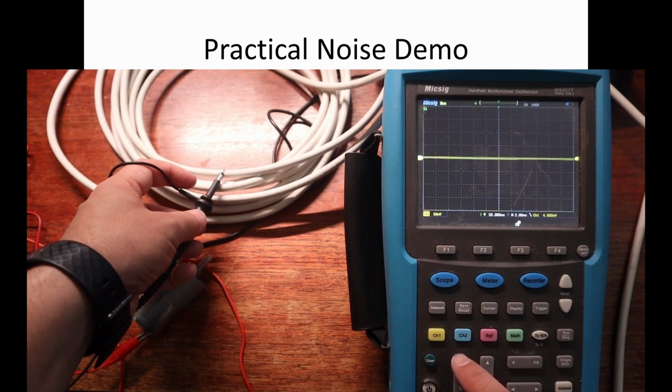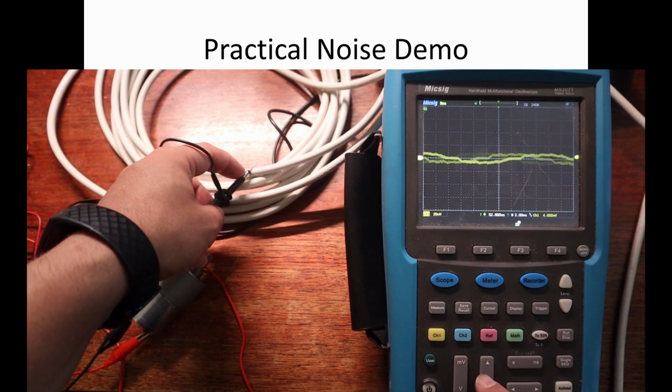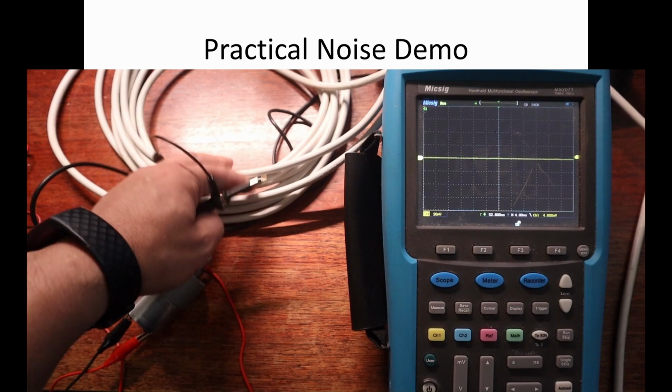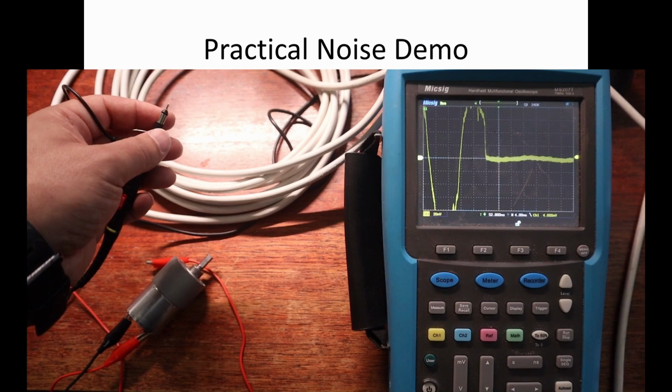We'll have to adjust our scale, and we should see we're getting a little bit of noise from being coupled in. And if I change our frequency a bit, we should see, there we go, that noise we're getting in there is at 50 Hertz. Now this power cable, AC current, 50 Hertz that we're getting there.